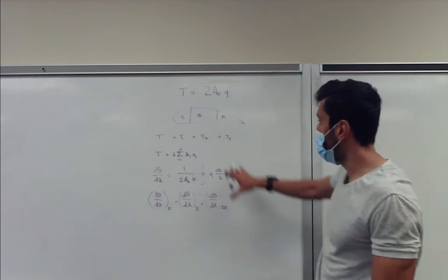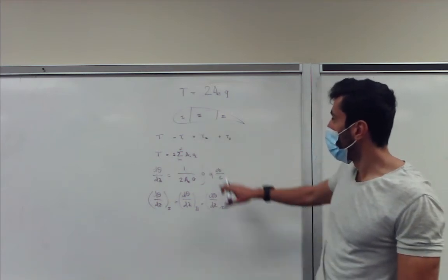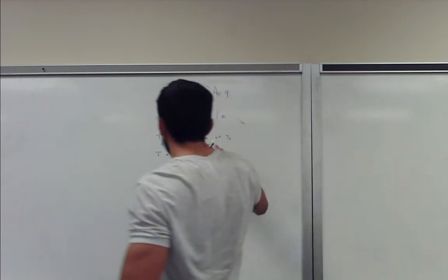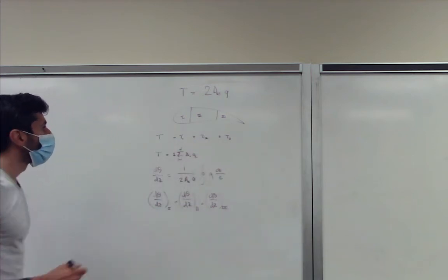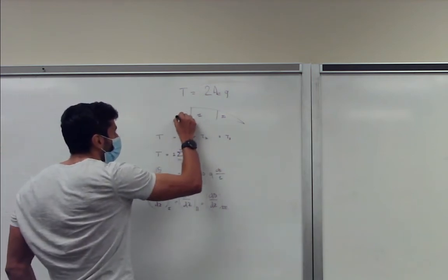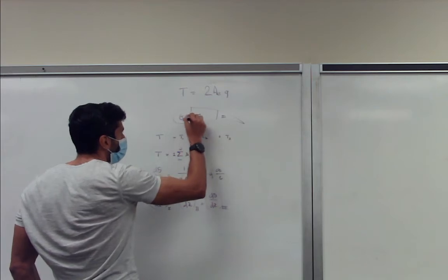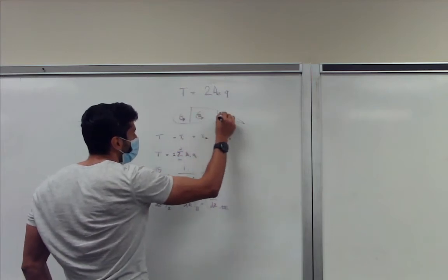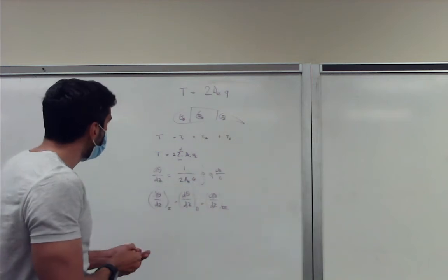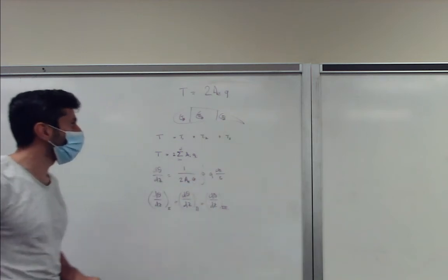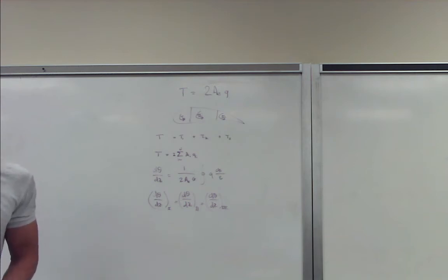If we go to the shear flow problem, we have three individual torques that form the total torque, so each of these will create a shear flow. It's important to draw the shear flows of each segment and then see what the effect is on adjacent members.